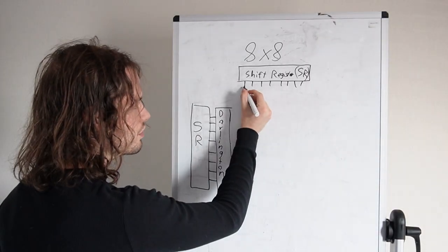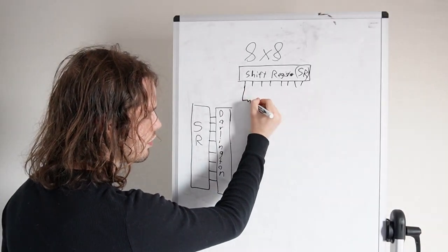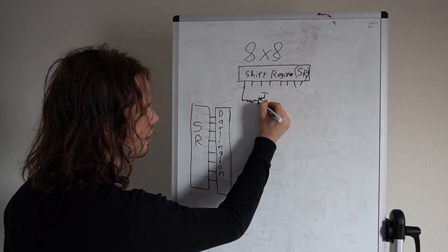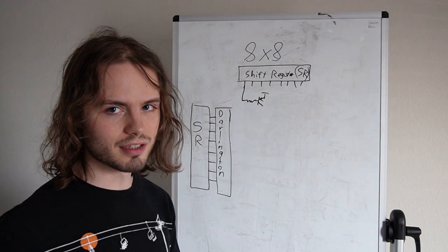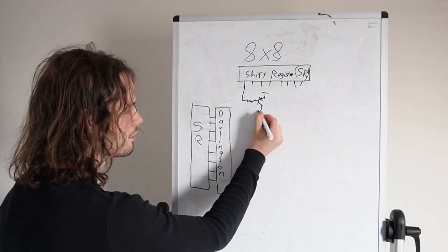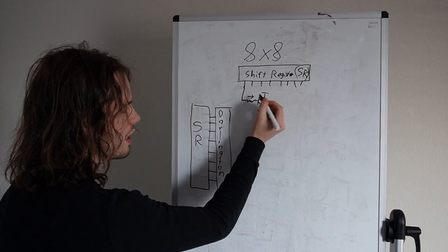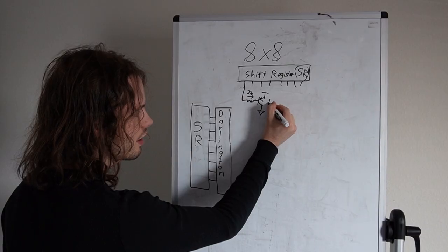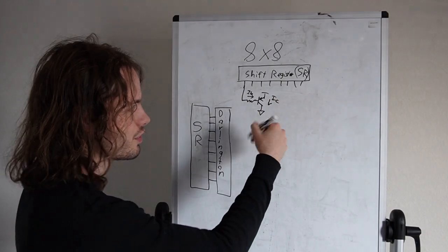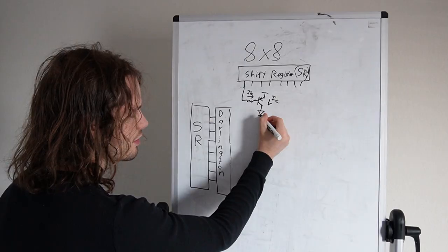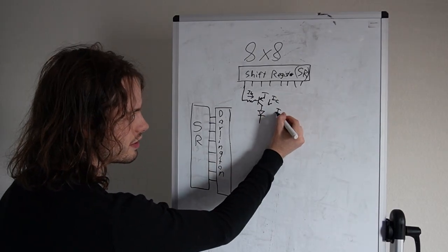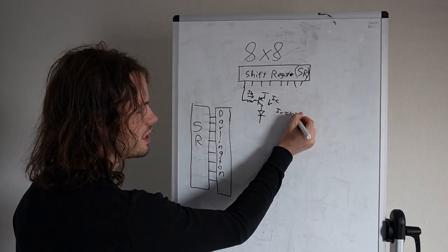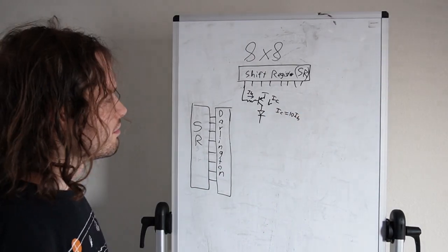So that's why I use the shift register as a control point, and I use a BJT to supply the current. I'm not going to go into too many details of how a BJT works, but just know that it amplifies the current here, so IB versus IC. I may have the direction of IC wrong. It doesn't matter too much. IC, when it's in saturation, I think I saw online, it's about 10x what IB is. So that's why I do it.